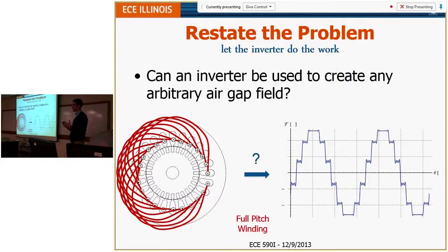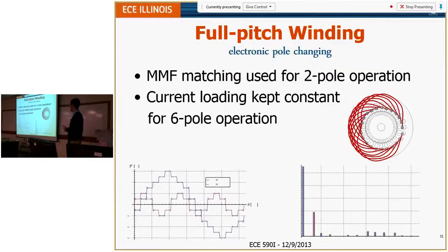It's actually winding a machine as a 4-pole and then making it a really crappy 2-pole machine by putting in contactors. So this is making it a really good 2-pole, and you're still making a pretty good 6-pole. The harmonics are nice. It just can't have as much torque as a 6-pole machine. I haven't really done any more than this right here.